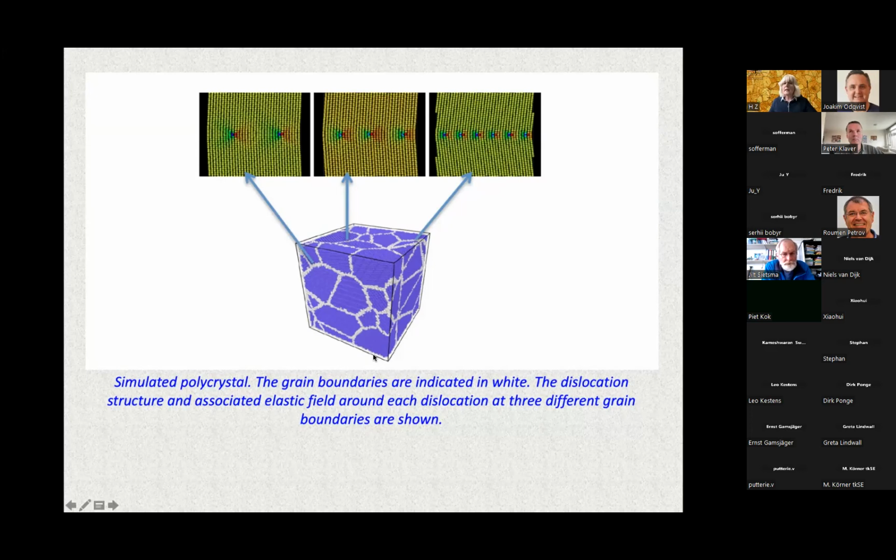We can also describe the situation in polycrystal materials. So here you can see the creation of the polycrystal materials. In the beginning, we introduce some number of nuclei with different misorientations, which can be, for example, a texture orientation if we rotate to some special direction, or just randomly introduced. In this case, it's just randomly introduced nuclei. And between the nuclei, we put the liquid and we decrease the temperature, and during solidification, we obtain the creation of the grain boundaries that you can see here.